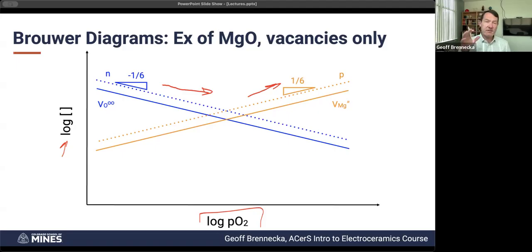The reason I heat it up is to allow the kinetics to be faster, or perhaps to increase the number of these defects that can be around. But generally, the reason we use furnaces is just for kinetics, because even for oxides, the kinetics can be really slow. I'm impatient, so I want this to happen in minutes instead of weeks.